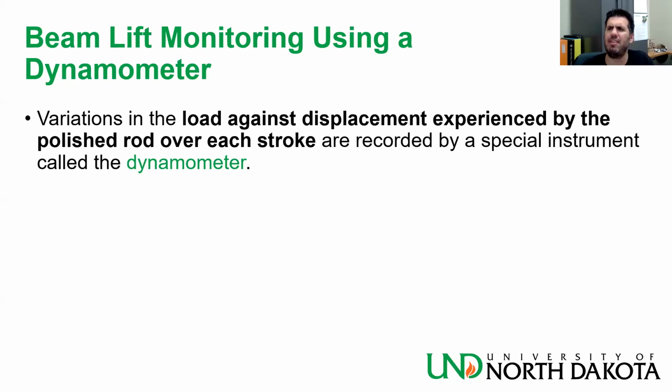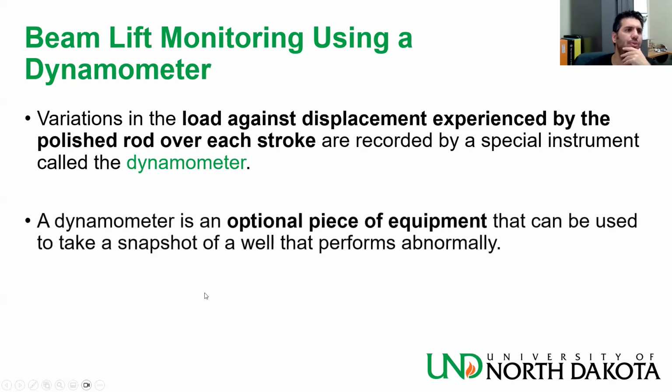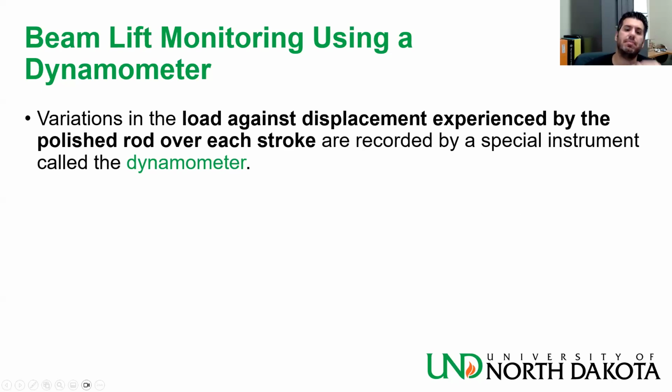I mean, it's quite a delicate piece of equipment for using it in a well. So what we do, it basically goes downstroke and then upstroke. In the upstroke, it weighs very heavily. So what happens is that the whole string extends. So if it extends, it becomes taller. It has a certain Young modulus. What happens in its width is that it's becoming narrower, slimmer.